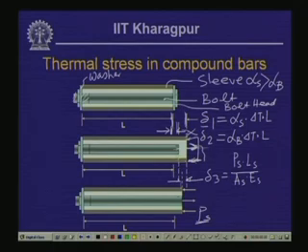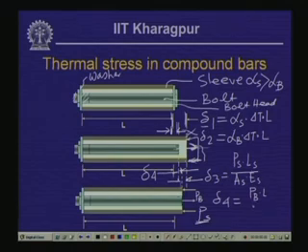This is the position after thermal expansion and this is the position where we need to bring the bolt. This deformation is delta 4, and delta 4 is equal to P bolt, if we call the central one Pb, times L by A bolt times E bolt. So, these are the 4 deformations that these members undergo at different stages.